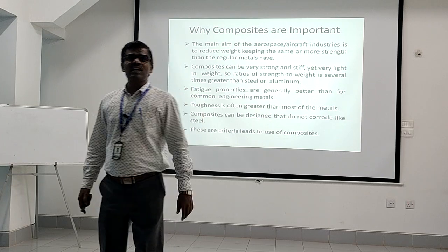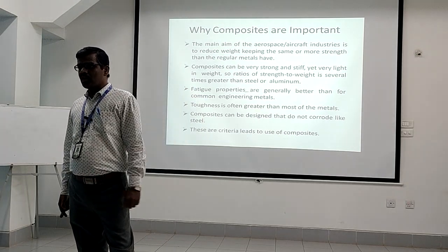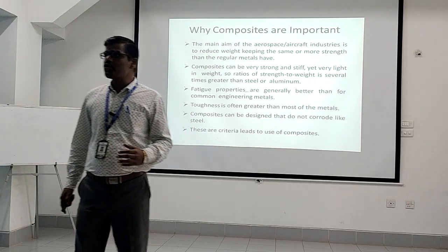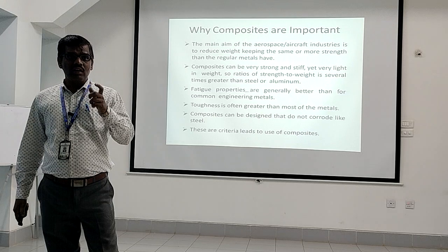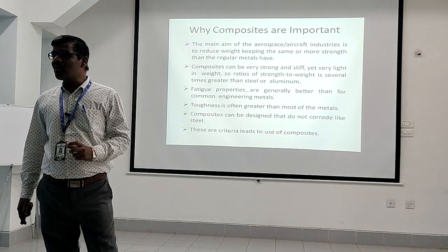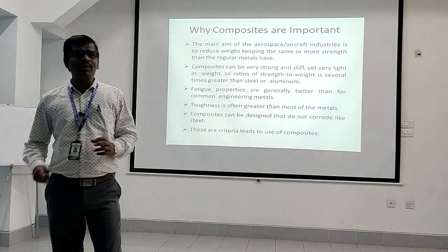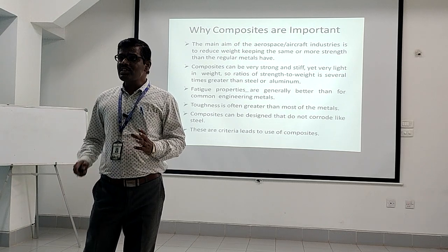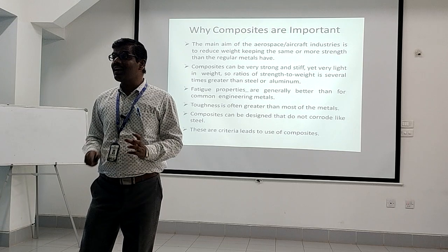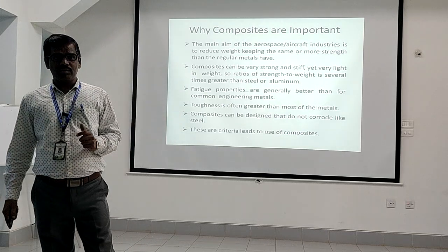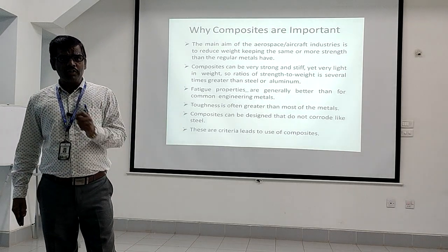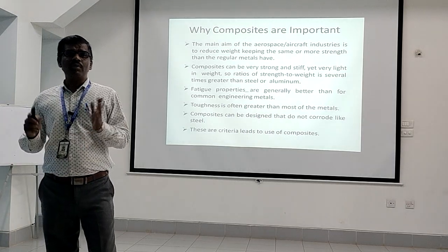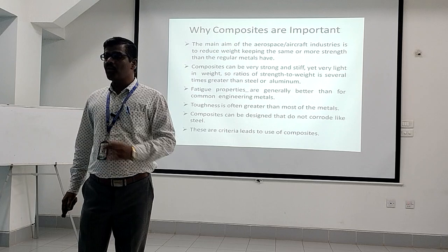I will take one more example: sports shoes. Before release to the market, sports shoes undergo fatigue loading, that is nothing but cyclic loading. Why do they conduct the fatigue test? To find how much fatigue strength that material has under cyclic loading. You got it? Composite material has better fatigue strength compared to normal engineering material.